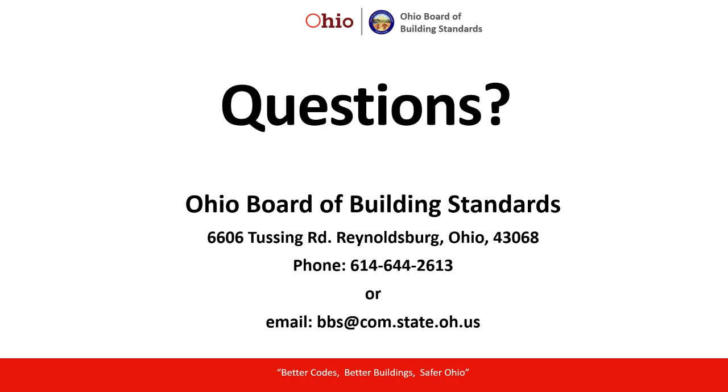I can say that a B&B, a bed and breakfast, is actually addressed in the Ohio Building Code. If you have a bed and breakfast, it is already addressed in the Ohio Building Code. It is a non-residential property. It's going to be in a single-family dwelling that houses or has 5 or fewer guest rooms, and they classify it as a group R3.